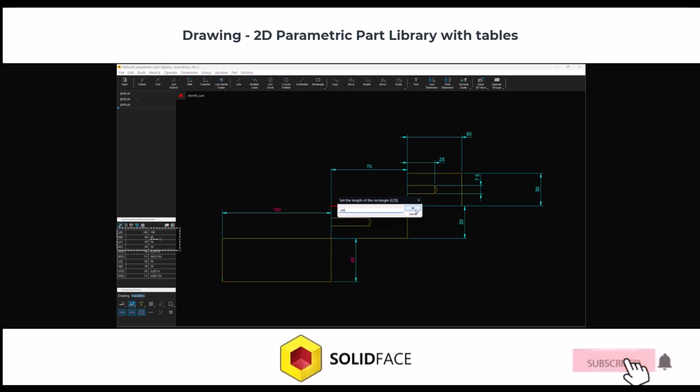It explains how to manually define dimensions for features like holes, using control key commands. Also how using standard dimensions and to link dimension values with variables, simplifying editing and association processes. The importance of tables in defining multiple variables is highlighted, showcasing how tables created in programs like Notepad or Excel can streamline parametric part creation. Associating tables with drawings allows for efficient management of numerous variables and variants in technical designs, emphasizing practicality in complex projects.